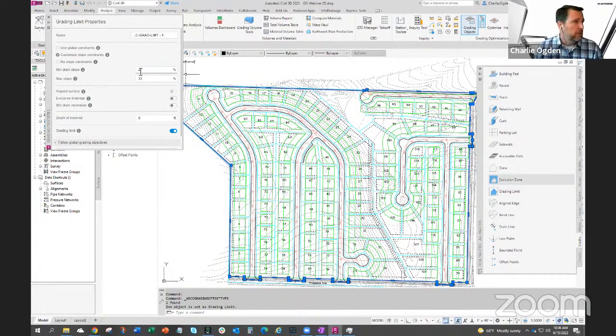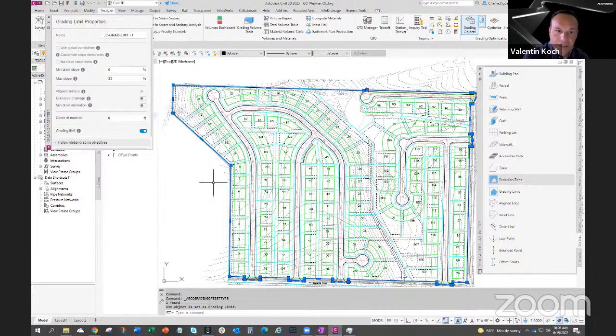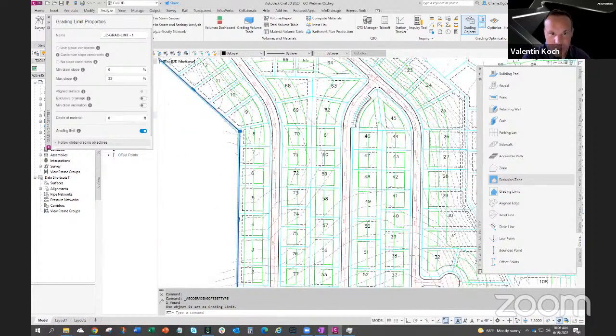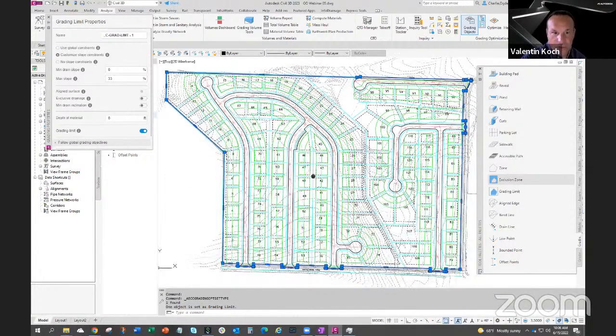And I'm gonna put that to 0. The reason is because if you put that to 2 like it was, there will be like inclinations towards closed drain elements or whatever, but we want it to be free to go and shape wherever it wants, the triangles, if they don't have to drain to a specific place.